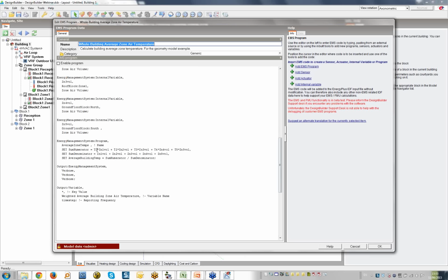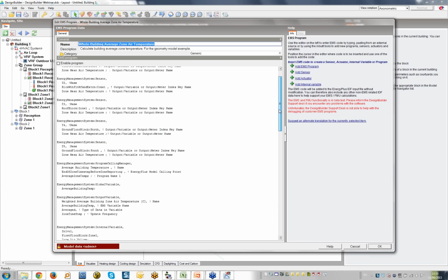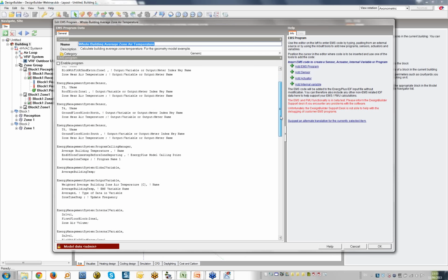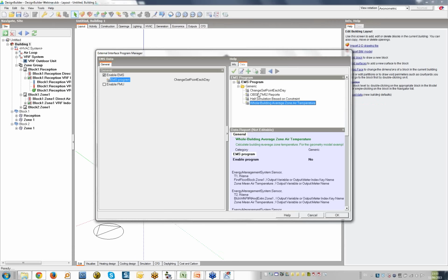And in the case of the schedule being changed based on a reference to a sensor, essentially what you do is set the new value. You override the value for the actuator. So we've got an actuator in this. Now again, this is a read-only script. I haven't got a very good example to show you here, but essentially you write code which overrides the current value of the schedule based on the sensor value and various other code that you could write.